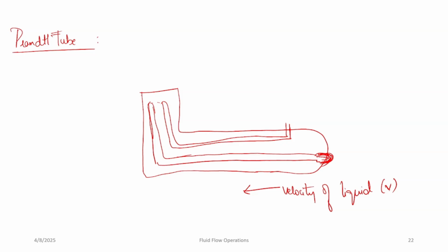If the velocity is very high, that means a supersonic velocity, it violates the assumptions of Bernoulli's equation, and the measurement will again be wrong. At the front of the tube, a shock wave appears that will change the total pressure.